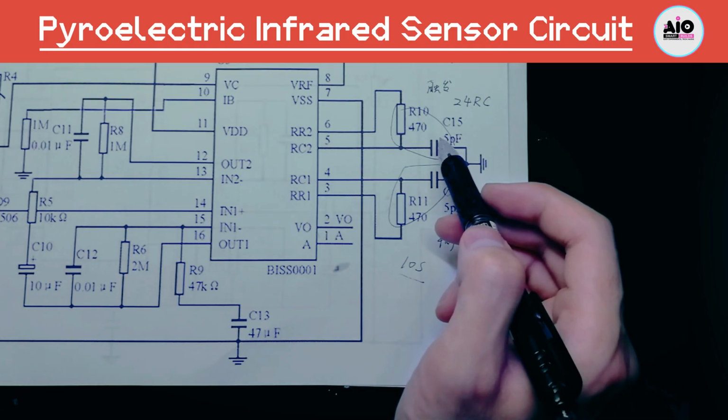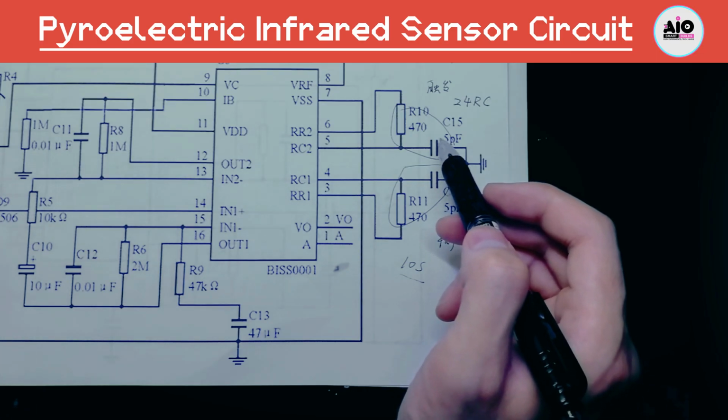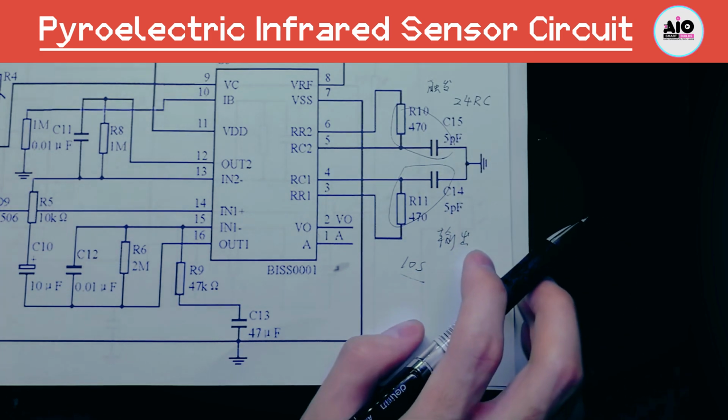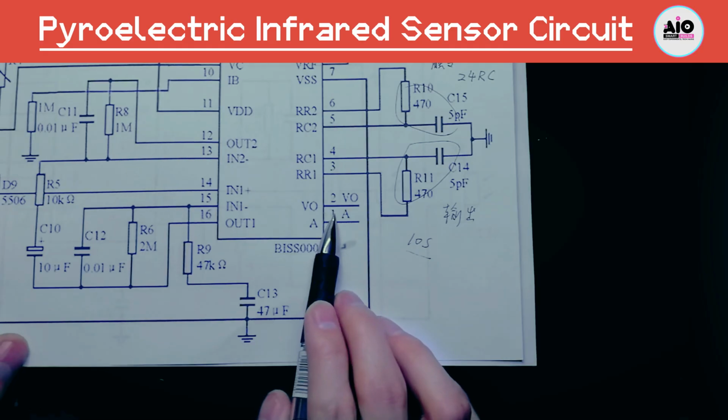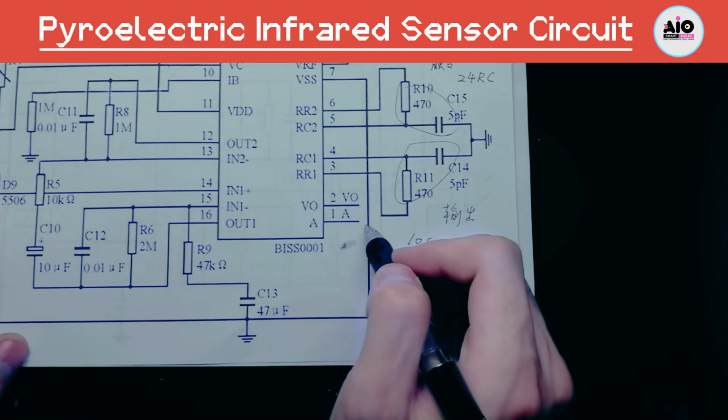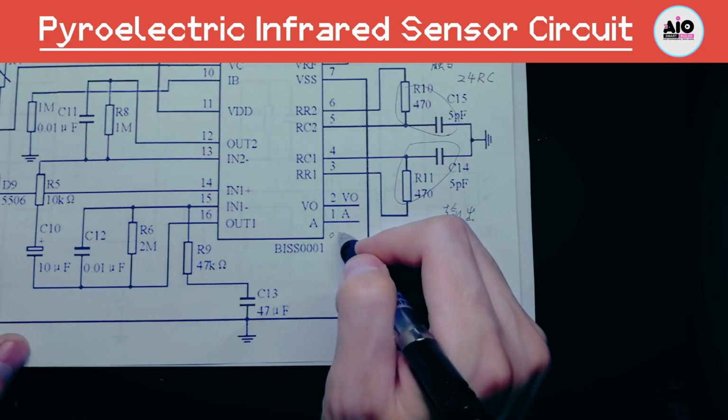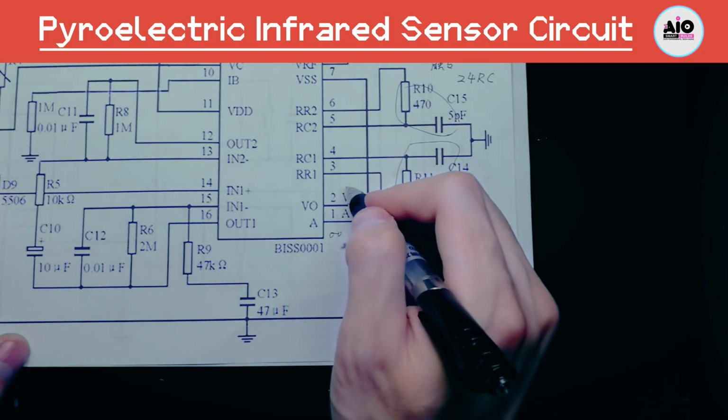Then the trigger blocking delay above is mainly to improve the anti-interference ability and also achieve the purpose of energy saving. When there is repeated movement, a blocking time will be added. Within this time, it will not be triggered, achieving the purpose of non-repeatable triggering.